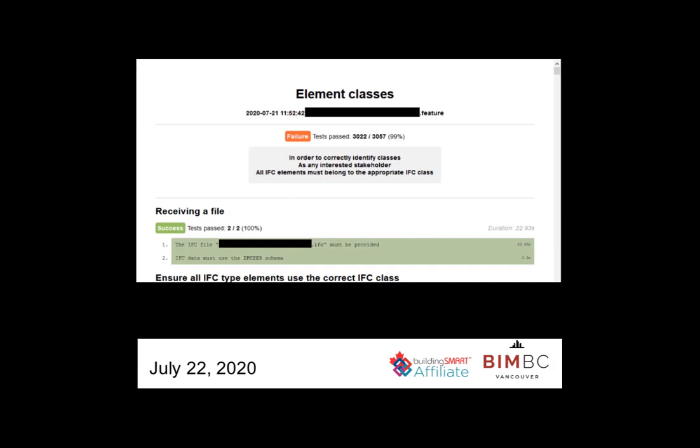This is another feature that Blender Bim has. It's something I call Bim Tester, again, developed as a separate module. And some of you may have used tools like Solibri or I think Simple Bim or something, which lets you audit the data in an IFC file. Basically say, is this parameter filled out? And if it is filled out, does it contain this content? And things like that. Or is this object in this room? Or is this person assigned to this object? And so on and so forth. So this lets you do that, but in an open source way.